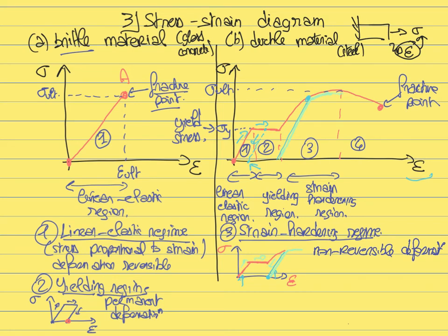So you will have more strain hardening. So why is this called strain hardening? It's called strain hardening because after you load and then unload the material a first time, the material becomes harder. Remember what we define as meaning of harder. Harder means more resistant to plastic deformation. So what does it mean here? Why is it harder?